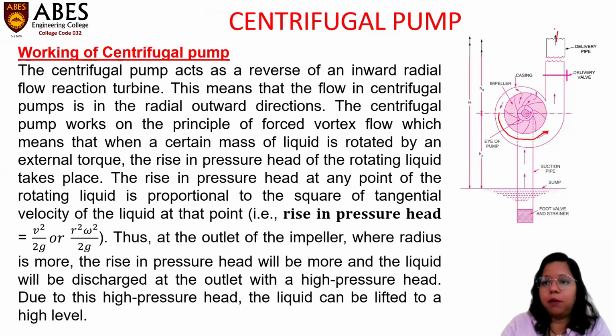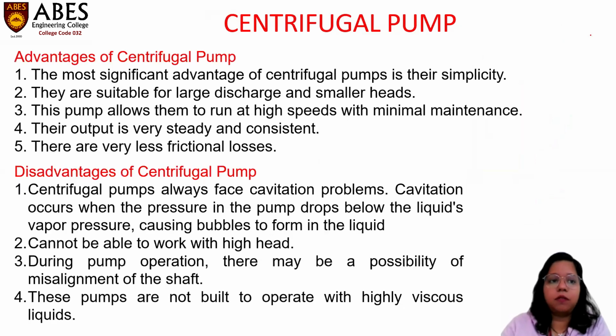From here, the liquid will be discharged. Due to this high pressure head, the liquid can be lifted to a high level. The water is lifted from the low level to the high level. So this is the working of centrifugal pump.